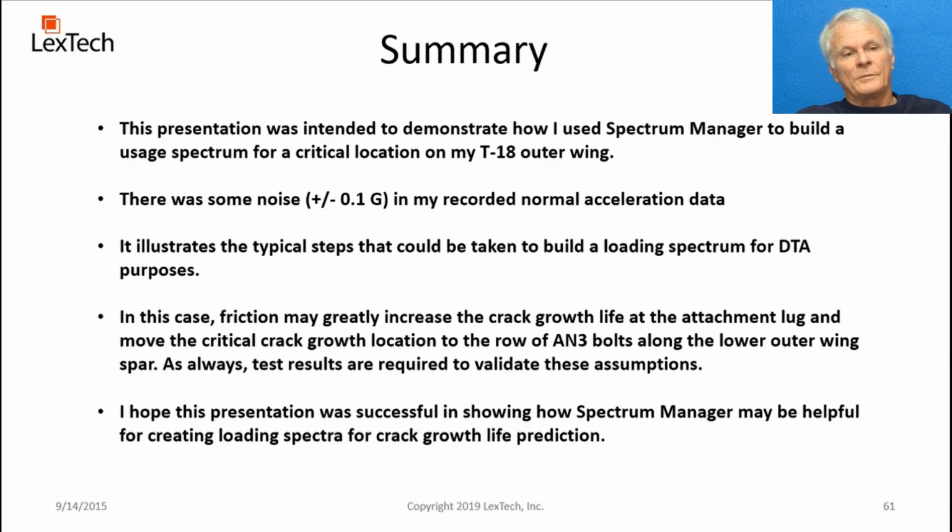Now, as I said, this would move the critical location, if true, to the row of 6 AN3 bolts along the upper spar from that fitting. But to be sure, you would always have to run a test. There's just no way to be sure without validating this. And again, I hope this presentation was helpful in showing you how Spectrum Manager could be used to create a loading spectrum for growth life prediction.